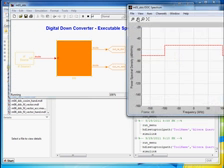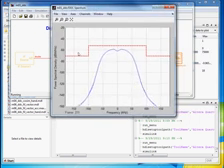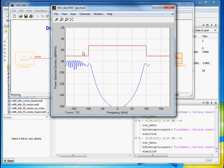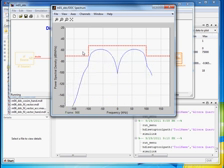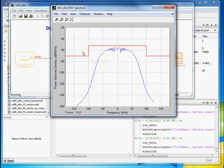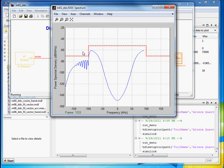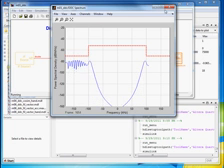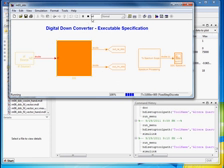So we'll go ahead and start a simulation running. And in red here we see the specified threshold for the DDC, and the blue signal is the evolution of the spectrum response as we feed in this chirp signal. So this is our intended behavior for the design.